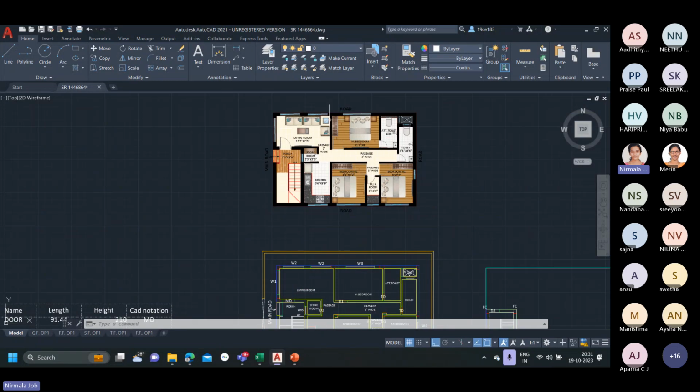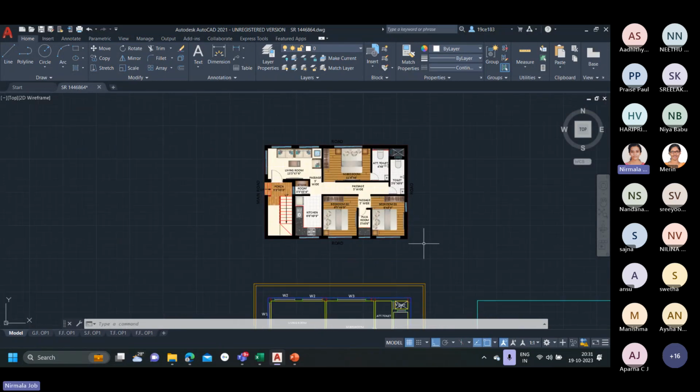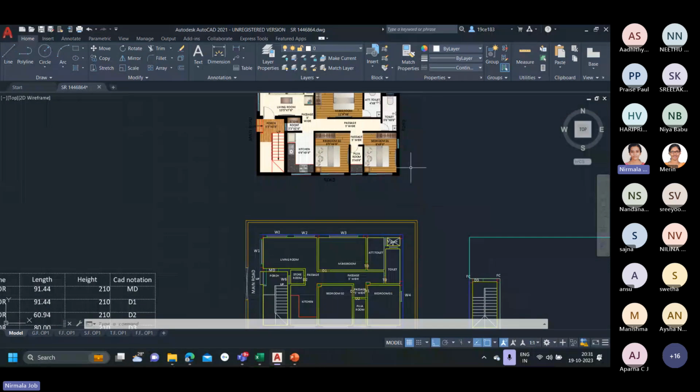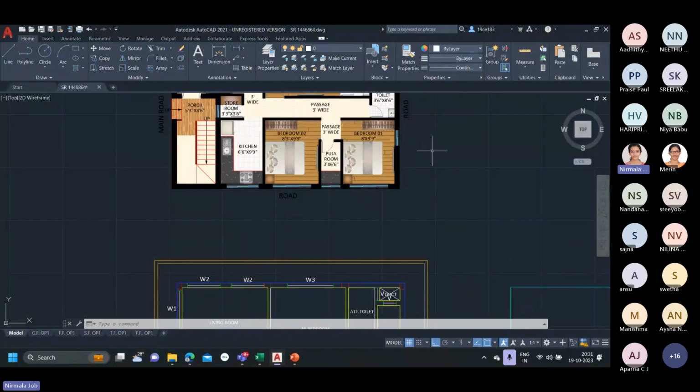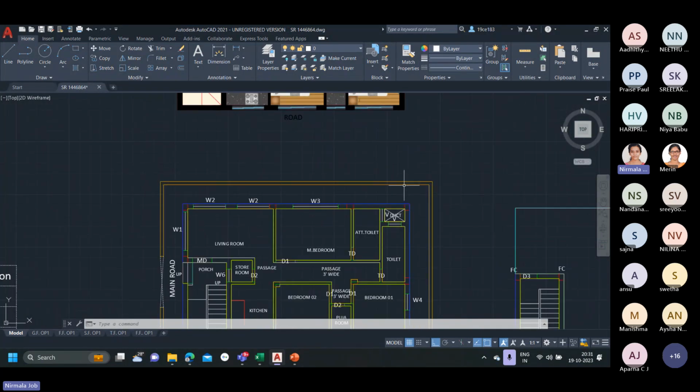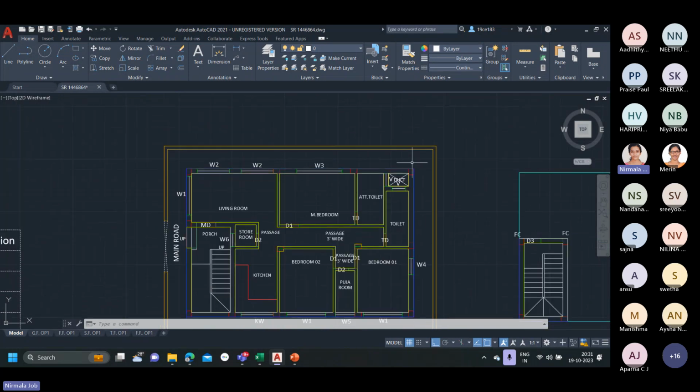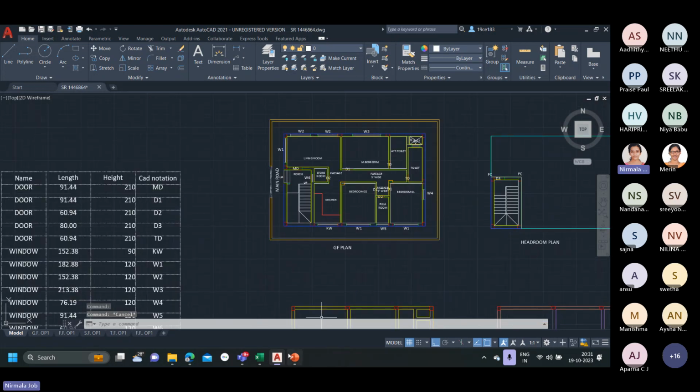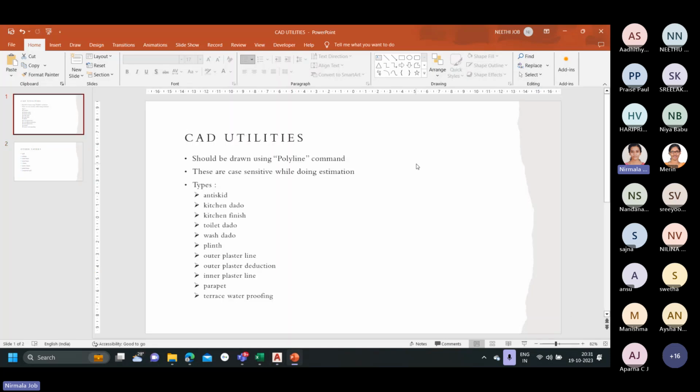In my figure, no compound wall is mentioned. If the clearance is not provided in the client drawing, the basic concept is that the ideal clearance provided by us in the UTech projects is 3 meter. So this layer is a compound wall, and it should be provided within a clearance of 3 meter from the building if it is not specified in the client drawing. So after that, coming on to the other set of layers that has to be assigned, that is commonly called CAD utilities.